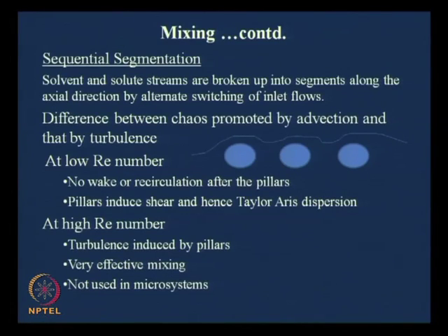You know the Reynolds number; at the very outset I said the Reynolds number came to about 1. So the Reynolds number is very low, and there is no way you can have turbulence there. At low Reynolds number there is no wake or recirculation after the pillars. Okay, that is absolutely not possible.